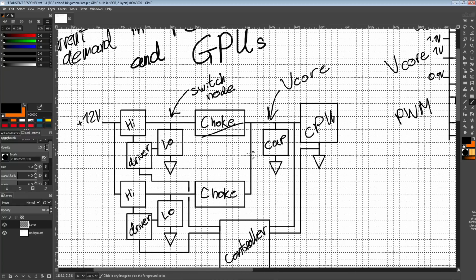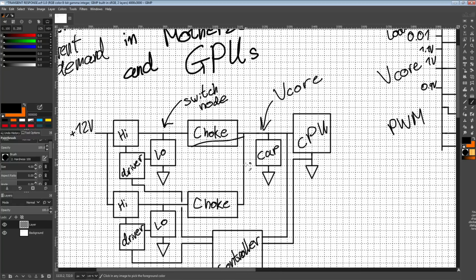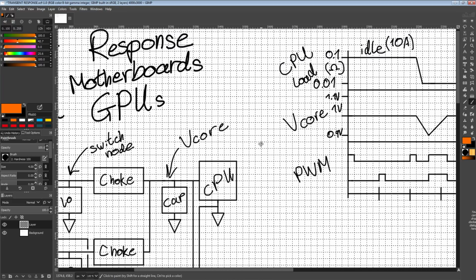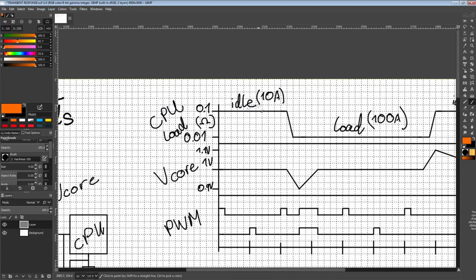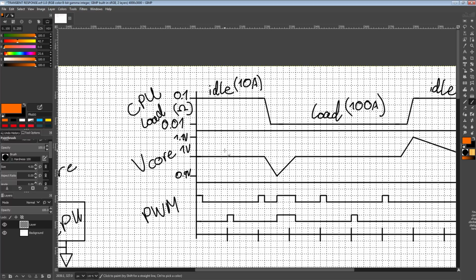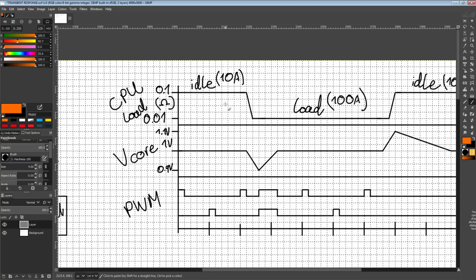So anyway, yeah, we rely on these inductors to do the voltage conversion, and the problem with this is they don't really do changes in current very quickly. That's just not a thing they do. So worst case scenario for this transition right here from idle to load, which is where you get the transient, right? You can see the connection there. Though I'm not sure that's actually the origin of the word, so don't quote me on that, but it makes sense to me, right?